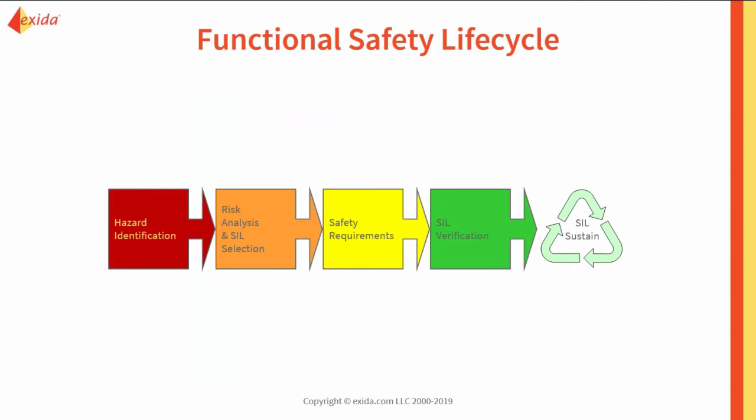When we think about functional safety from the end user's point of view and the SIF point of view, instead of just thinking of what is happening or what could go wrong just in that valve, they're instead looking at what can go wrong from a hazard point of view. So first of all, we want to know what possibly can go wrong. We look at what the process is and what you are protecting against. What really is the risk? Are you in an ammonia plant in the middle of a cornfield with a very toxic, very dangerous substance? Or are you generating power in the middle of a city right next door to an elementary school? No matter what your condition is, no matter what the risk of the process is, you want to consider what can possibly go wrong. And the end users do that through HAZOPs or PHAs.